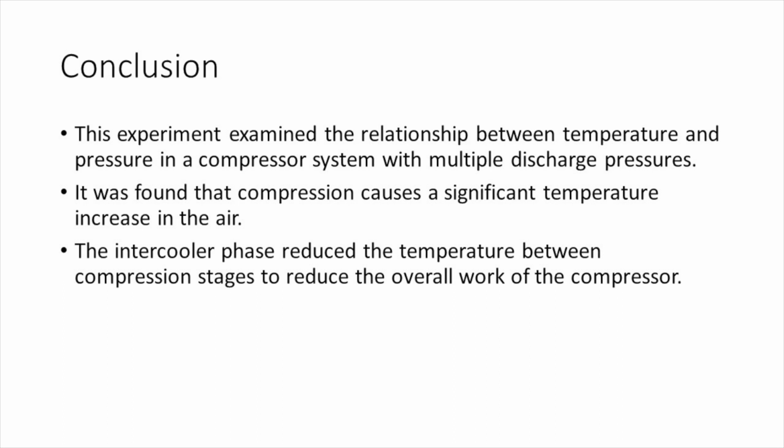Conclusively, what we did in this experiment was to investigate the relationship between temperature and pressure in a compressor system as we vary the discharge pressure. The biggest thing that we found was that during compression, the temperature of air actually increases. And that's why we have an intercooler phase in a two-stage compressor, which will reduce the temperature between the two stages so it can be compressed much further.